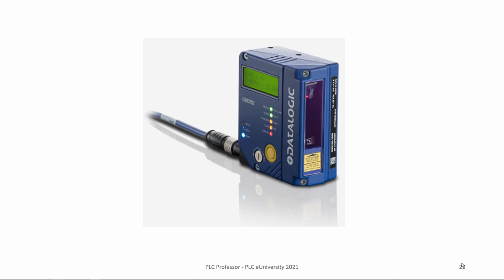Now, some of these barcode readers can read horizontal or vertical or in a full 360 degrees. It just depends on the design. This looks like a one axis only, meaning that it scans up to down. So for our application, it would probably be laid on its side so it was reading horizontally, the laser scan. And everyone's done enough with barcodes, like at the gas pump, you hold up your card and you can see the laser scanning across it. Barcode reader, and it has a trigger. Something needs to trigger it. In our case, that's photo I1.